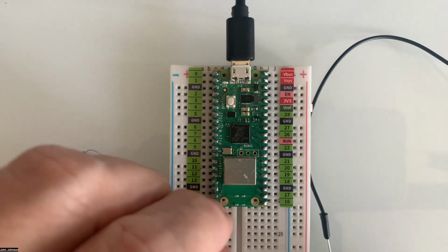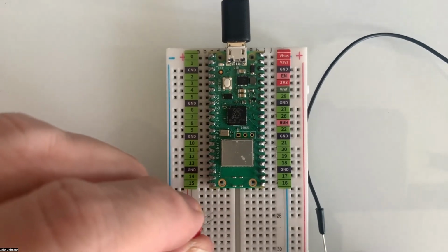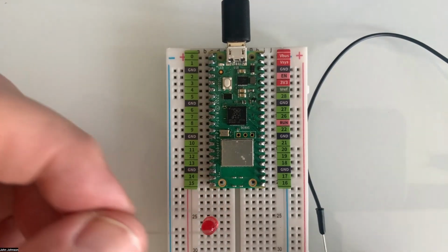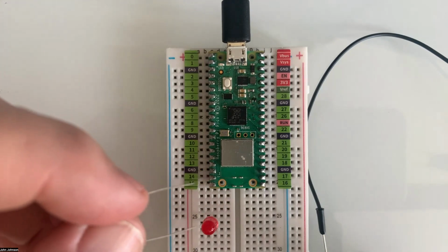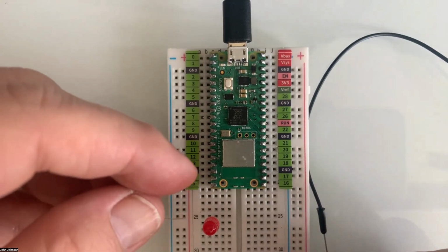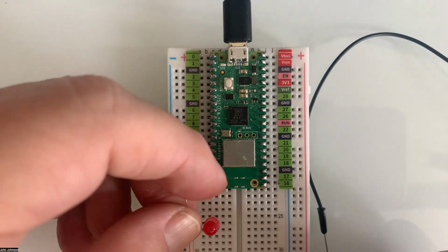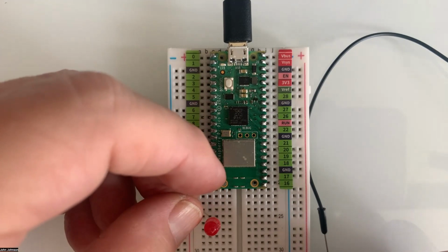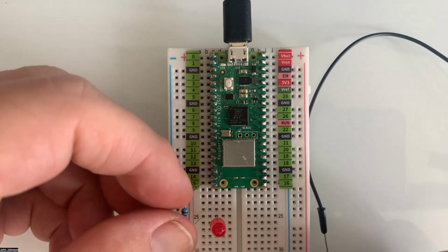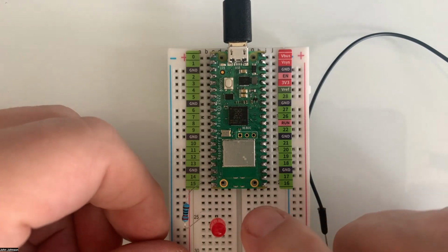Now let's bring it down a little bit more because we want to give ourselves a little bit of space here. So the longer one is on top. Then I'm going to take our resistor, and our resistor is going to connect pin 15 to our positive terminal here. So I'm going to put one end right here on 15. So I've got one end on 15. Then I've got the other end, which is going to go to the positive side here. So hoping you can see that. I've got one on pin 15, and then I've got one down here on the positive end.